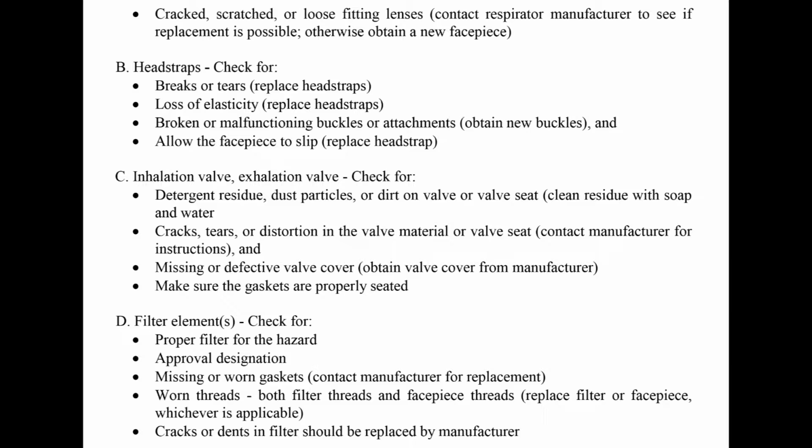B. Head straps. Check for breaks or tears: replace head straps. Loss of elasticity: replace head straps. Broken or malfunctioning buckles or attachments: obtain new buckles. And if the facepiece slips: replace head strap.